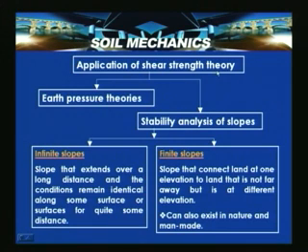You might have learnt this shear strength theory. With that, two possible aspects are very important. One is earth pressure theories and the other is stability analysis of slopes, and these two rely entirely on the shear strength of a soil. In earth pressure theories, we understood how we can compute earth pressures on a retaining wall. Now, in these lectures, what we look into is how we can analyze a slope or arrive at a safe slope in case the slope is unstable, and we look into methods for enhancing the stability of a slope.